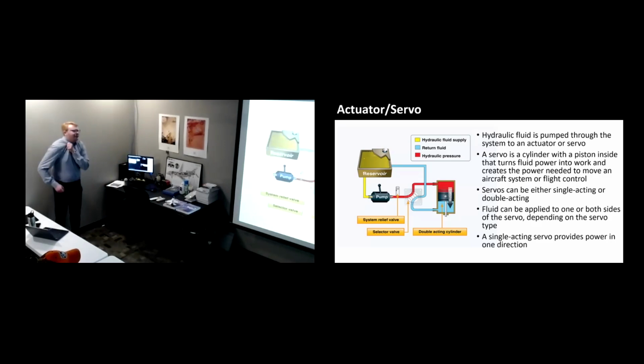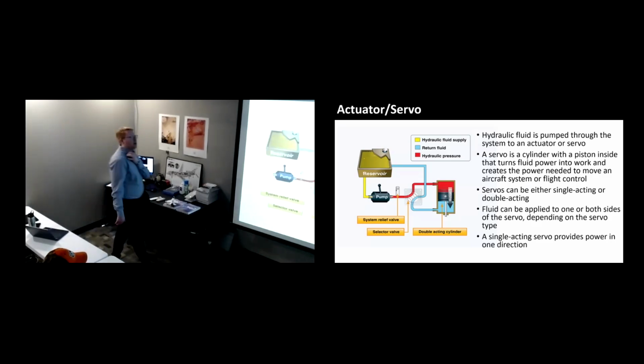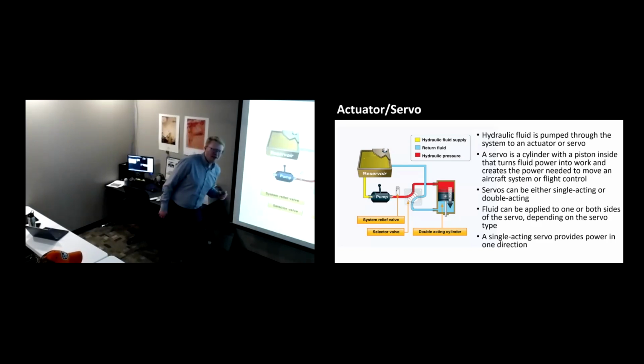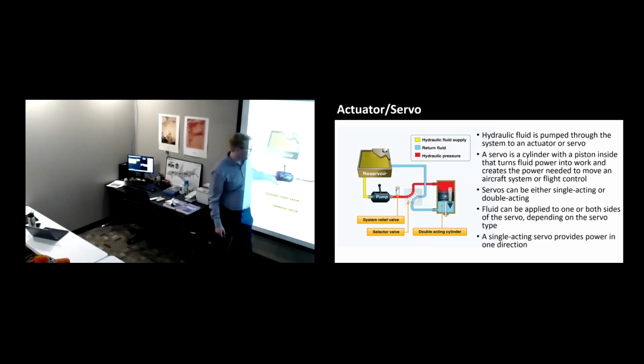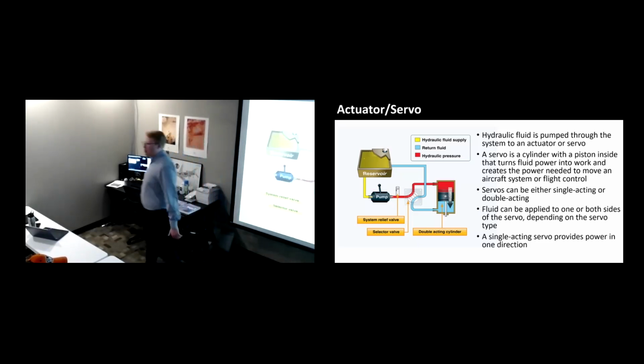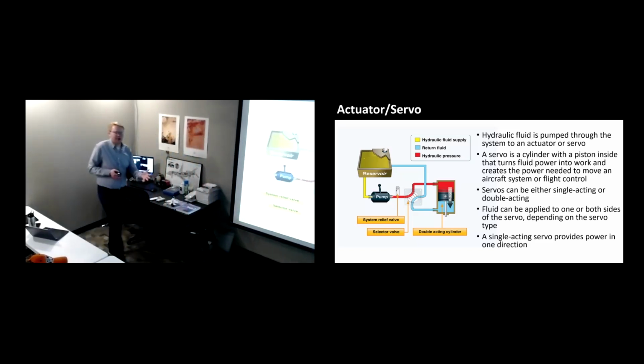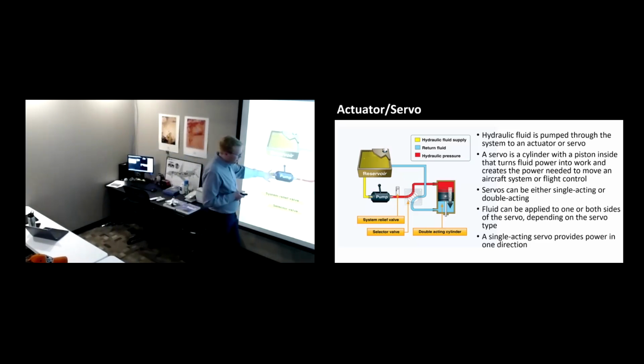Okay, so I'm not going to dive into too deep details. We don't need to understand it at 100% level. Essentially, imagine a loose concept of a piston inside of a cylinder. Loosely, imagine this piston here, this tube, if you will, or cylinder, has a fluid on either side. We call it hydraulic fluid, and it's connected to the reservoir, and fluid flows on one side and the other. And there's a pump connected. If I were to pump fluid into here, it would push the piston down. If I were to pump fluid on the other side, it would cause the piston to go up. So all I'm doing is pumping fluid into one side versus the other under a lot of pressure that this pump causes. And that pushes the piston up and down. That causes this rod to move in and out.